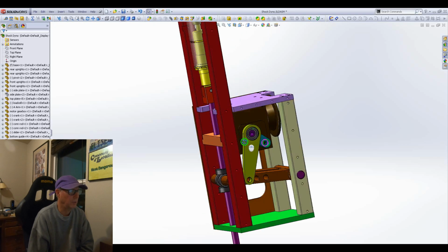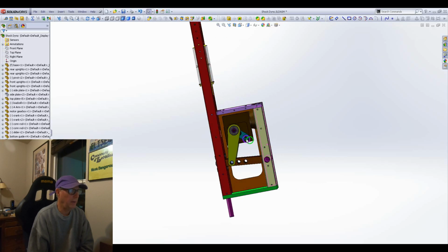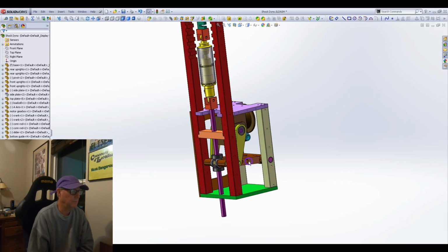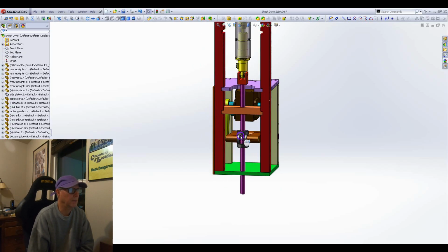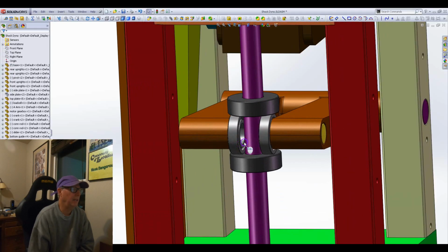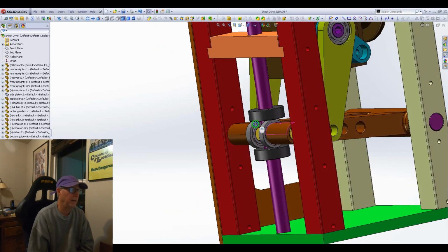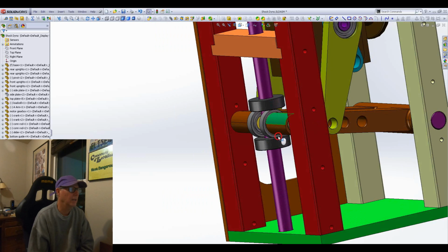And this particular one has two different strokes, so you can change the stroke of the crank, and you can also change the stroke of the piston by changing where the connecting rod goes into this A-arm kind of setup. Unfortunately, this got kind of complicated because this thing's got to go straight up and down, and then this A-arm is going to articulate, so the hypotenuse can get shorter, blah, blah, blah. So it has to have these roller bearings here and these pusher puller things.